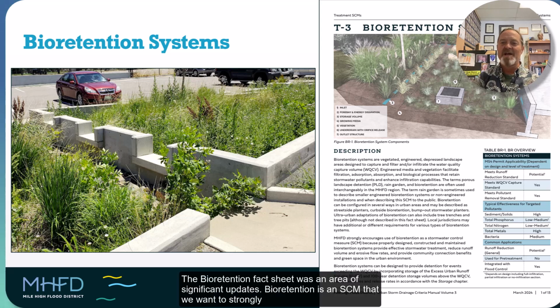The bioretention fact sheet was an area of significant updates. Bioretention is an SCM that we want to strongly encourage due to the runoff reduction benefits, the effectiveness of treating runoff, and the potential to provide stormwater facilities that are attractive rain gardens to the surrounding communities.